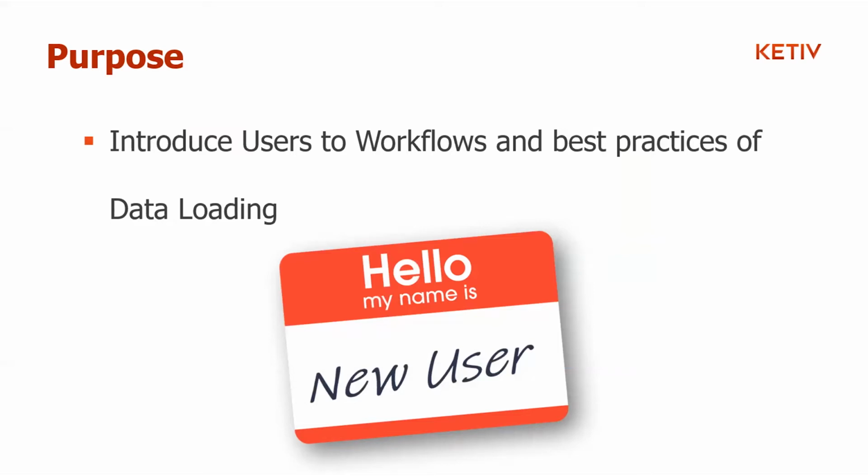Clean data means that whenever you open it up inside of Inventor, there are no broken links, there are no reference images that are missing, anything like that. Because as we'll see in a little bit here, there is actually a check that Vault Autoloader does to make sure that it's good to load, that there are no broken links, that it's able to open it up once it gets uploaded into the vault.